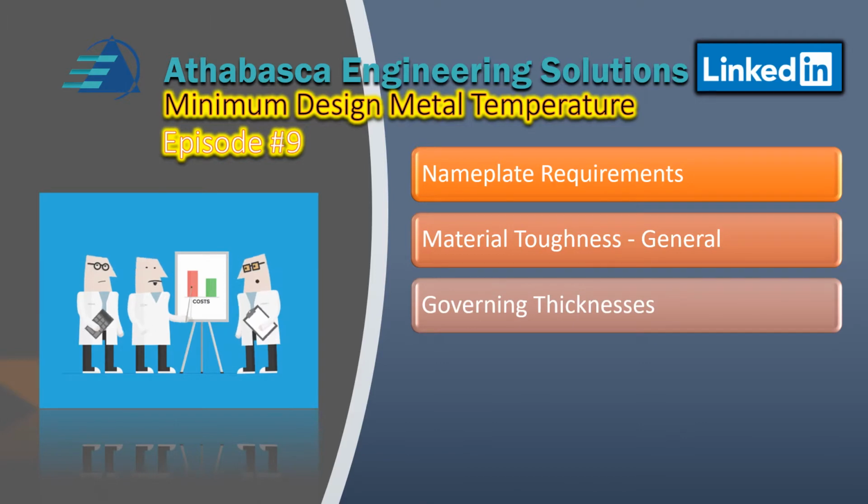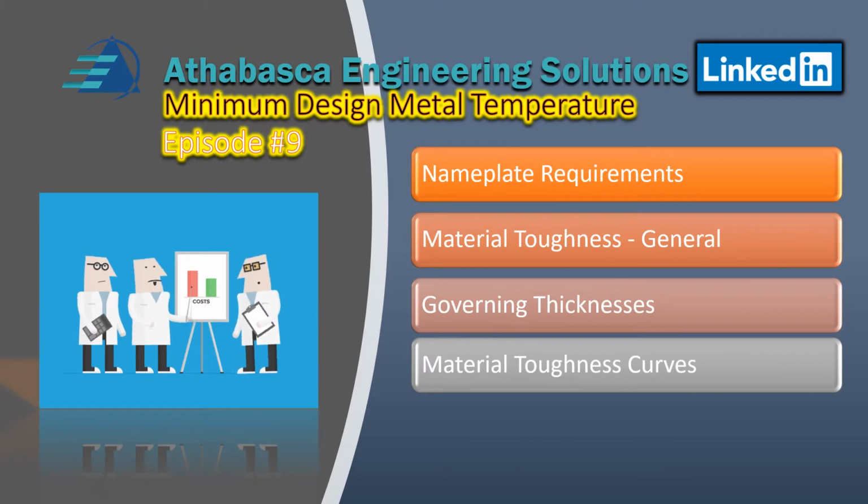Thirdly, we'll talk about governing thickness and how it relates to Division 2, and a little bit of discussion on how it compares to Division 1, and some material toughness curves. You can see the differences from our earlier presentations to this one, how they're different and how there's more factors to consider in designing it, because it's more of a precise type of calculation or determination.